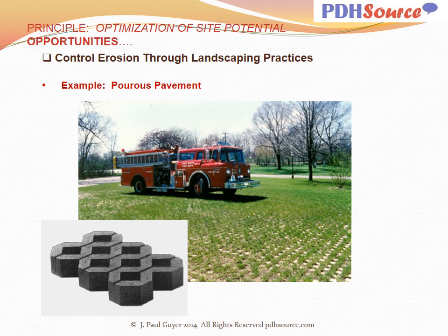And so rather than paving this entire area with asphalt concrete and with the resulting sheet drainage that occurs with asphalt pavements, you would be using these paver blocks. The cost would probably be greater, the initial construction cost, but if you've got the money in your budget, this might be an option. And it provides an attractive landscape feature. We've all, I'm pretty sure, probably seen a number of these installations, and they can be a nice feature on a site.